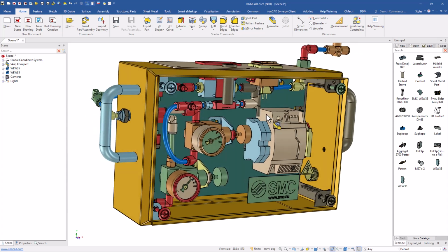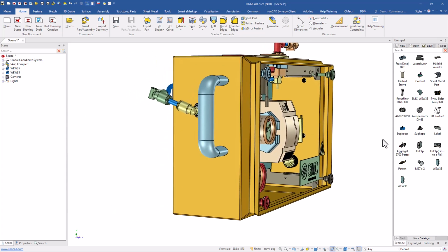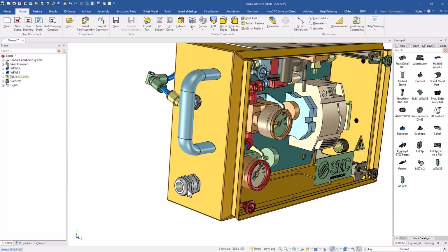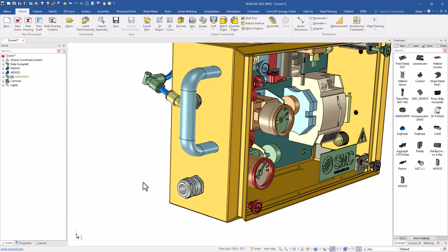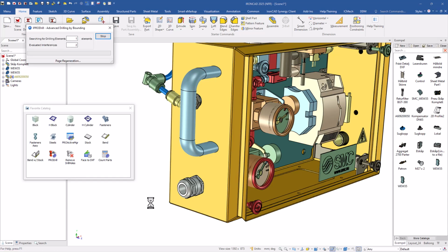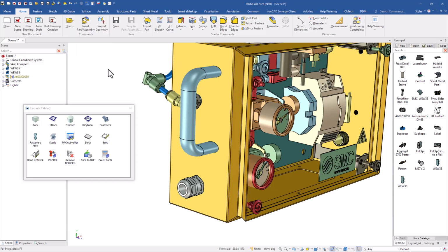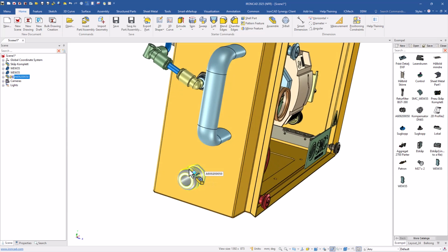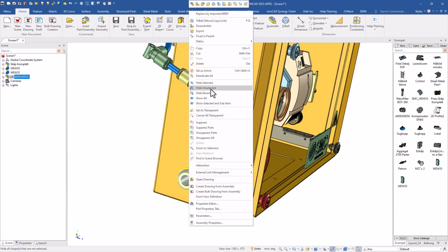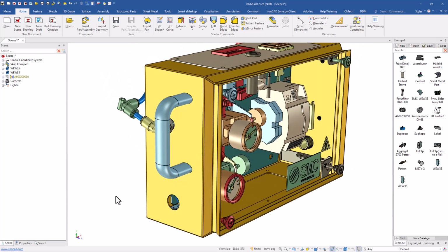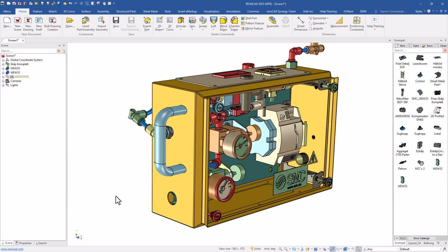And furthermore, you have the possibility to create a hole when needed. If you have this kind of components, you can drag them in a separate assembly, and I can choose C for the shortcut to my favorite component. I just drag in Pro Drill. Now it's checking the whole assembly for holes that should be created, and it is now a hole for this component. This hole property was included in the part I have in the catalog. So it's very, very fast and easy to work with drag and drop and cabinets in IRONCAD.